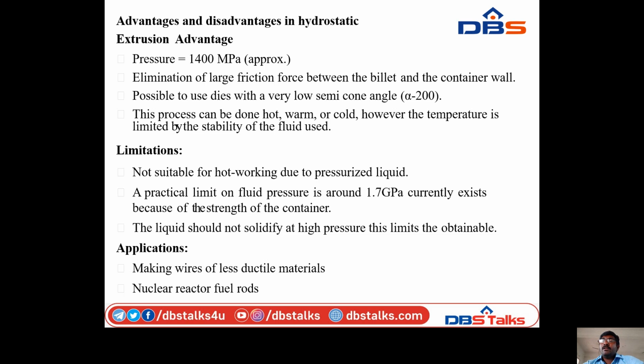This process can be done hot, warm, or cold. However, the temperature is limited by the stability of the fluid used. Limitations: not suitable for hot working due to the pressurized liquid. A practical limit on fluid pressure of around 1.7 GPa currently exists because of the strength of the container. The liquid should not solidify at high pressure. This limits the obtainable applications.